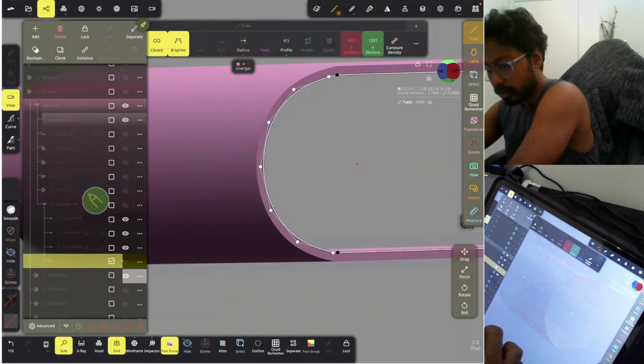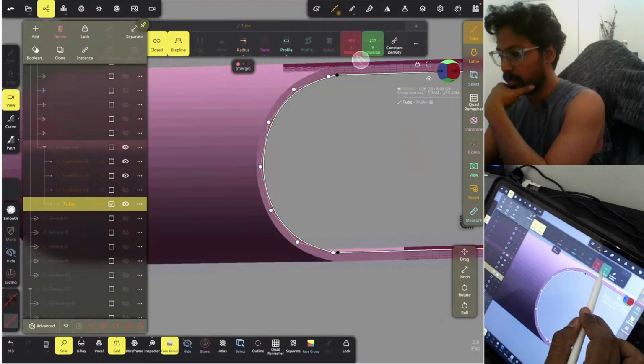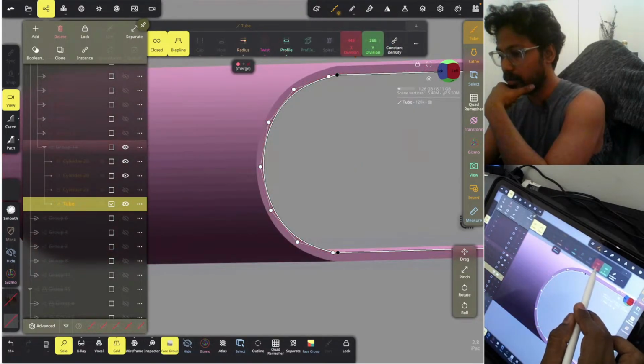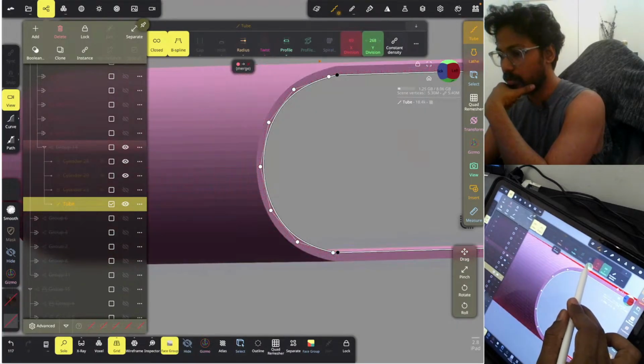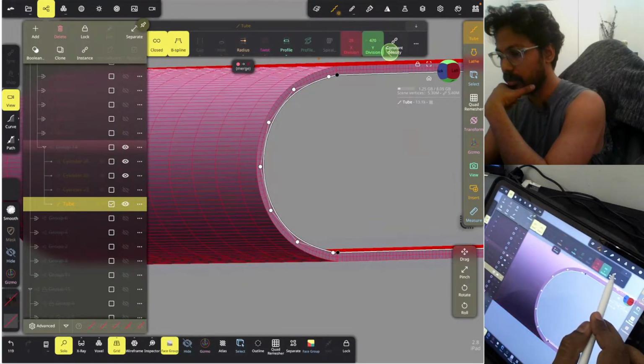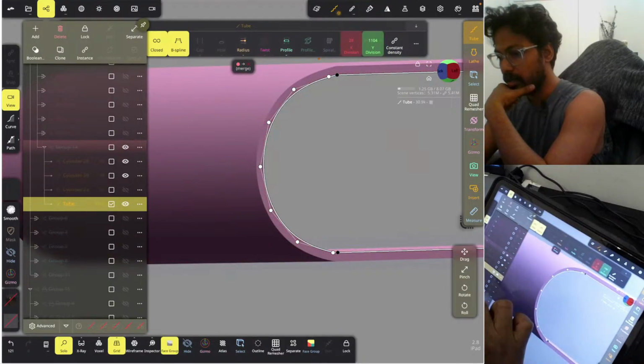In this case, we don't want to go beyond 100K, so we can reduce this definitely. Might go even further here, but you can increase this higher. So this gives a smooth surface overall, and your number of triangles is already 30K.